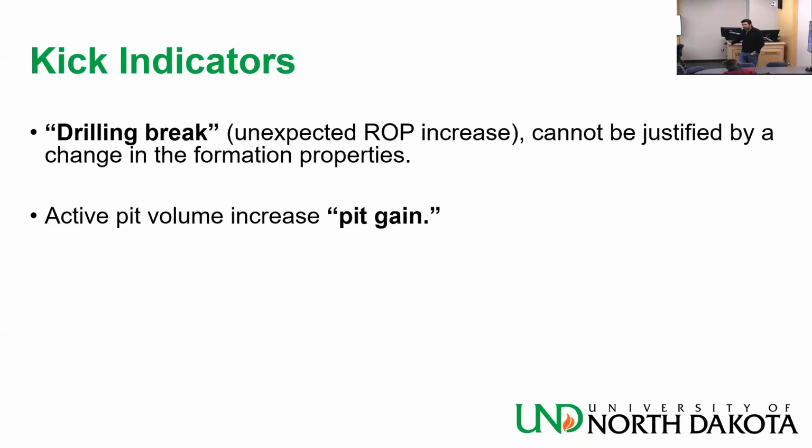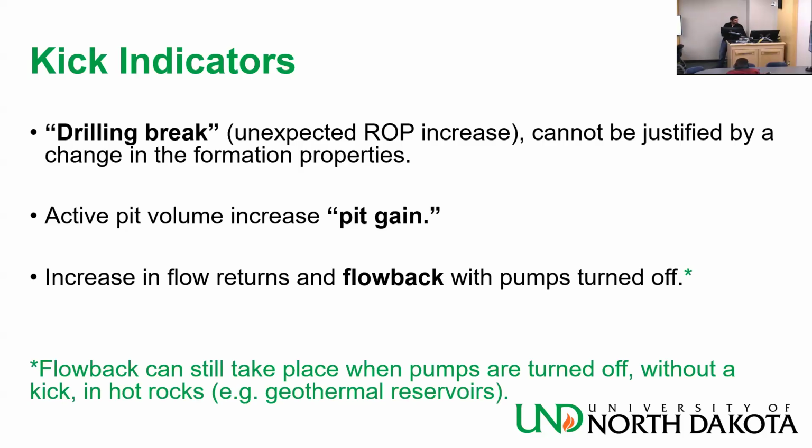But suppose you think you have a kick and you are not sure, what are you going to do? You're going to stop drilling, lift the bit off the bottom, and then shut off the pumps. If you shut off the pumps and you get flowback, it's an indication that you are getting a kick, right?